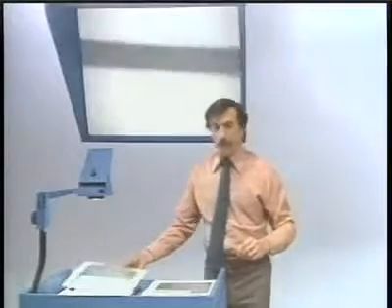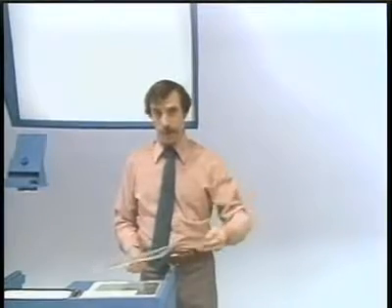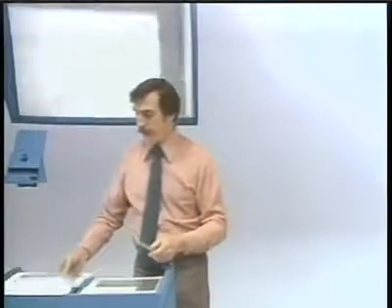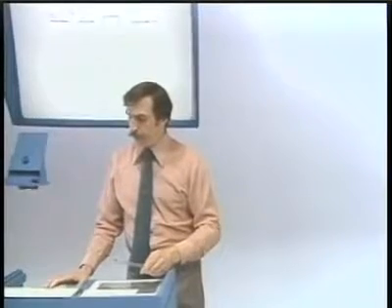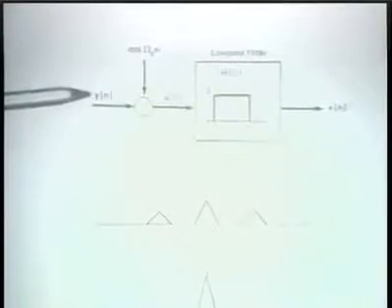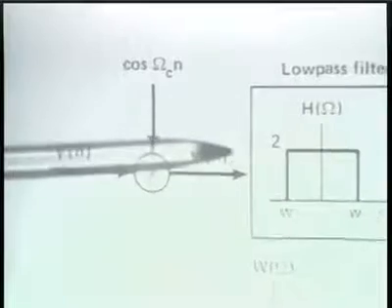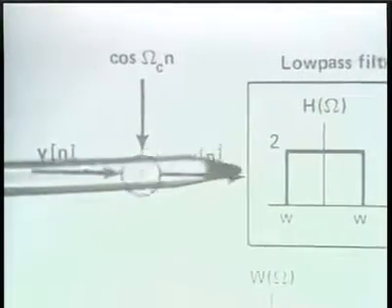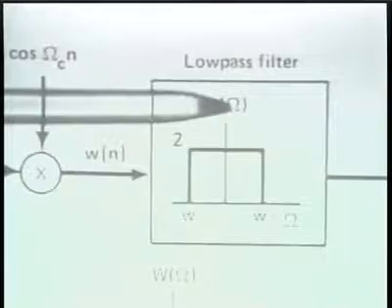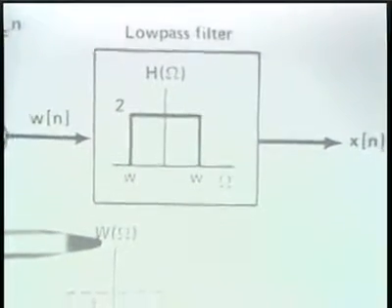So once again, things work out basically the same way as they had in continuous time. We have sinusoidal modulation, which consists of using a sinusoidal carrier, and we have the demodulator, which consists of taking the modulated signal, multiplying by the carrier, and then processing that with a low-pass filter to extract the portion of the spectrum which is around 0 frequency, as I indicate in the spectra below.